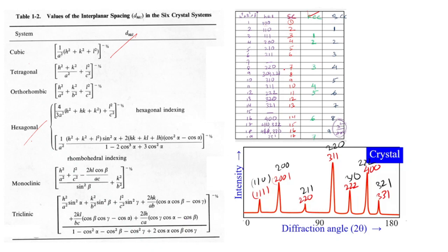So here you see we have the HKL peaks, and the simple cubic is taken as the base reference, and all the peaks are indexed. We will see how they are indexed in the next slide. As of now, just know that they are all indexed. So for the HKL, just remember this order: 100, 110, 111, 200, 210.